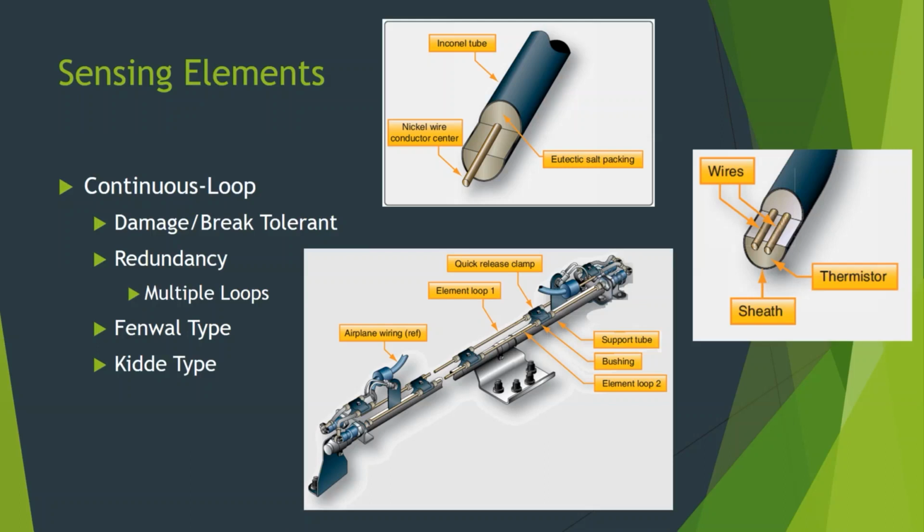But it would be something we would pick up during our BITE check, or on new aircraft with ICAS, it might give a left engine loop A caution. It tells you that loop, something's wrong with it, it's degraded. Now, if you know that one of those two loops is bad, if A goes bad or B goes bad, that's why on the 727 there's that switch that you can select A or you can select just B. And in the new computer airplanes now, if they've got the computer system, it does its BITE check, it sees that, it will automatically go into a reversionary status where it only is looking at one loop. So that's what you do when you switch that switch.